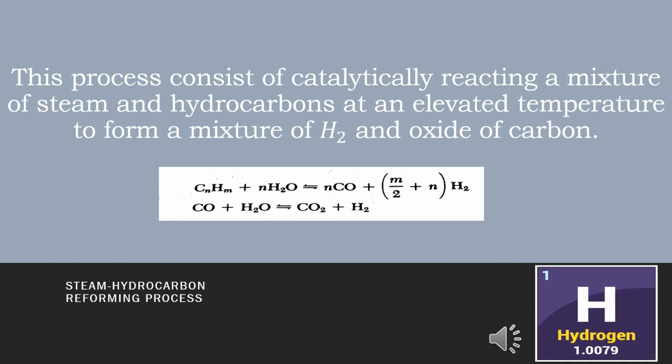With high concentration of CO in the feed, the shift conversion is usually conducted in two or more stages, with interstage cooling to prevent an excessive temperature rise. The first stage may operate at high temperatures to obtain high reaction rates, and the second at lower temperature to obtain good conversion.